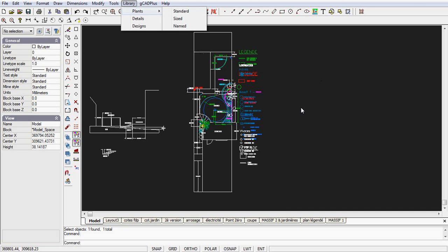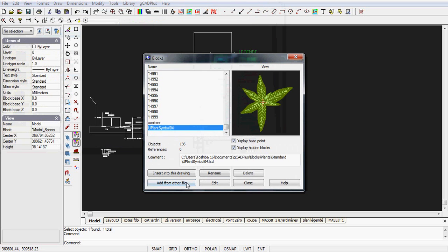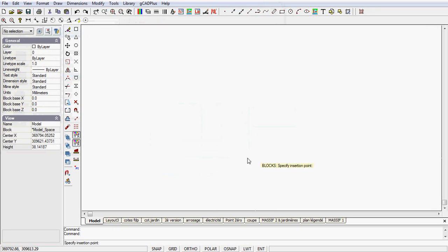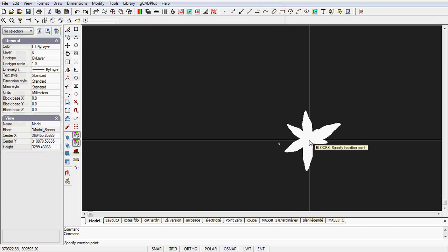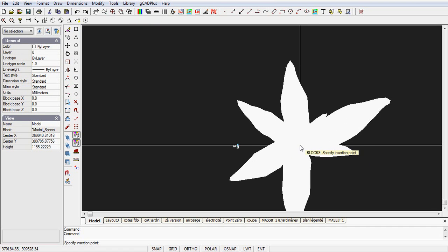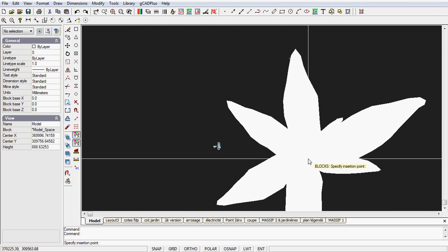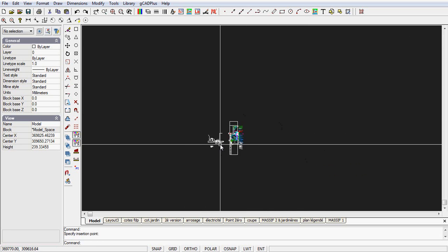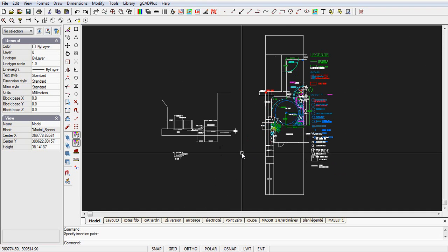drawing environment. If we work now with the drawing as meters, and we pick, let's say, a standard plant symbol number 4, and we try and bring it in and say insert into this drawing, you'll see this enormous great big symbol, which you can just see to the left now, next to the actual design. The symbol is 1,000 times bigger than it needs to be, so life becomes far too clumsy. I'll escape from there and we'll magnify. So we need to scale the drawing and make it millimeters because everything in the building trade is millimeters.